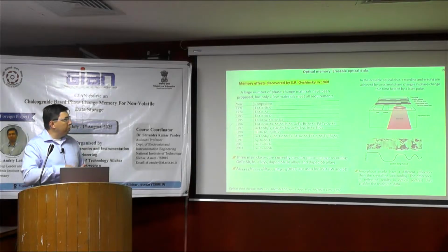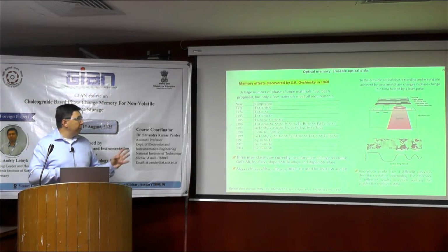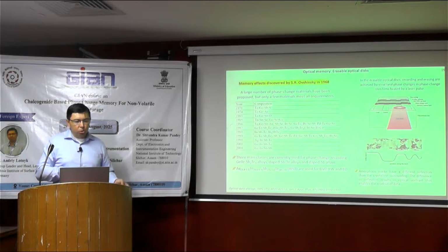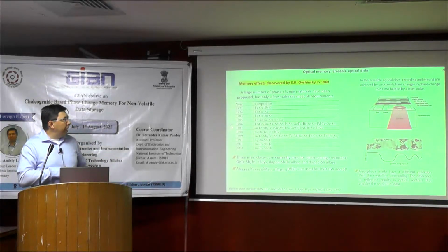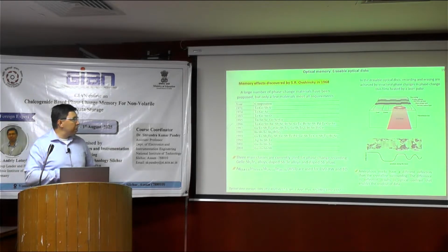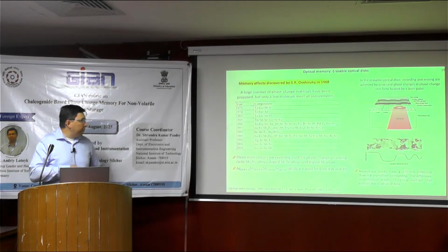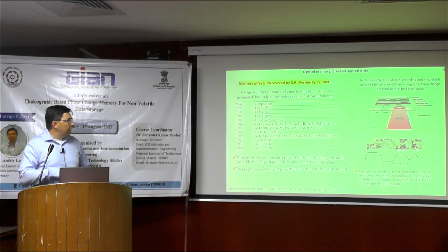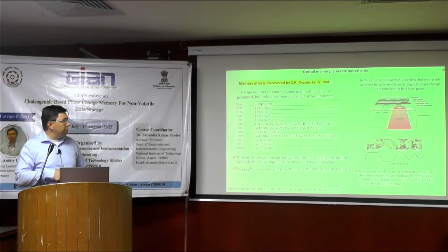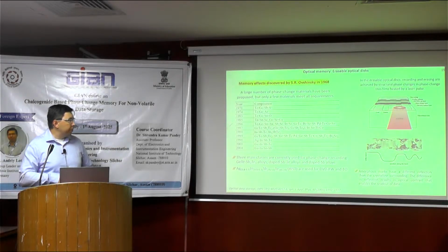There are a huge number of compositions which the research institutes or companies tested. And then in 1987, the Japanese group discovered the germanium telluride, antimony telluride system, and they showed very stable switching between the states. And after that, there are three main classes of phase change materials which are currently used for phase change recording. These are alloys based on germanium telluride and antimony telluride, also doped antimony telluride and doped antimony alloys.